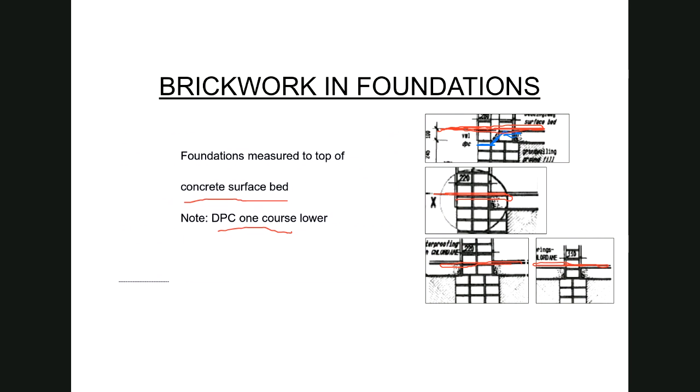And I want you to see this, and I'm going to color what I'm calling the complication in green. And this is this 100 millimeter high brickwork that is sitting in this position over here. So in every case, let me see, there are on detail 3 and detail 4. So where we will be looking at the foundation wall up to the height of the 245 dimension that we have over there, we still need to deal with the 100 millimeters that is just above that, because the 100 millimeters is underneath our cutoff line.